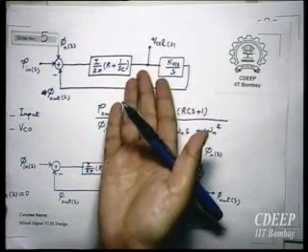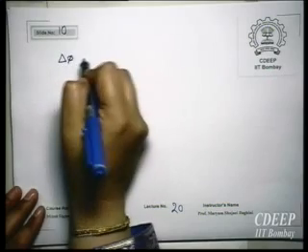So coming back to the same charge pump, and this loop we want to lock. Let me just show you the loop filter. Forget about these noise sources, just this is the loop. What this loop does is essentially generate some low frequency voltage, or essentially DC, which will be this control voltage, and then will generate the frequency. But what is the maximum phase difference I can have at the input? The maximum phase difference that anybody can generate, delta phi, always will be between these two values, right?